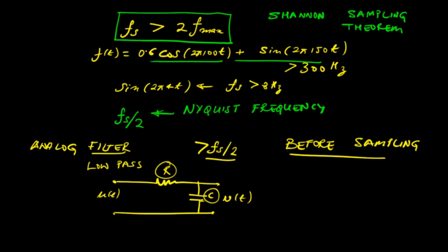So to summarize, what we've seen in this lecture is that FFT is an algorithm to implement the discrete Fourier transform, DFT, in a highly efficient manner, and in practice whatever DFT we compute, we do it using FFT. And we've also seen that we cannot sample the continuous signal at any frequency we want. That sampling frequency must satisfy the criterion that it must be greater than twice the maximum frequency component in the true signal. Otherwise, those high frequency components might be aliased and might appear as low frequency components.